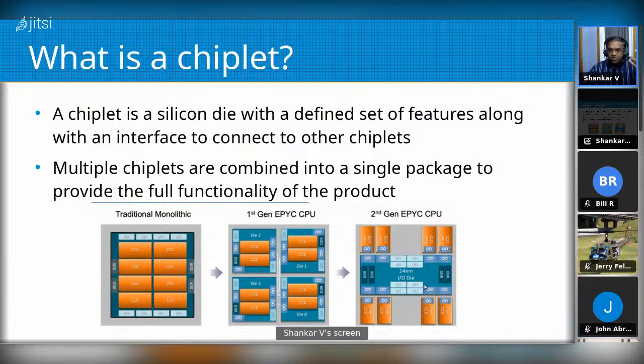Similarly, large caches don't scale the same way. So even if you were to put one of these memory controllers in this die, the size won't change from one generation to the next, or changes very little between one process generation to the next, because these are analog dominated, and analog circuits don't seem to scale as well as pure digital circuits.